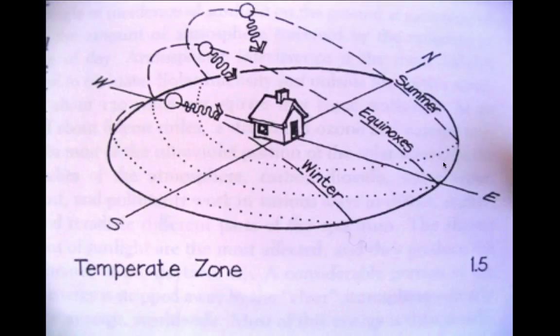And the rest of the year, when we're going towards summer from the equinox from March 21st going towards summer, then the sun every day is rising just a little further to the north of east, until it's quite far north of east and actually shines on the north side of a building in the morning and afternoon in the summertime.